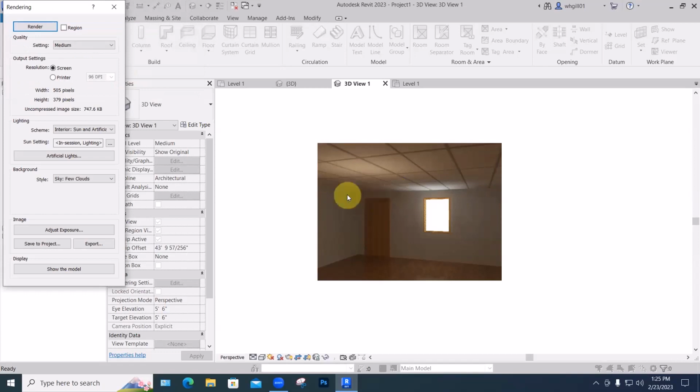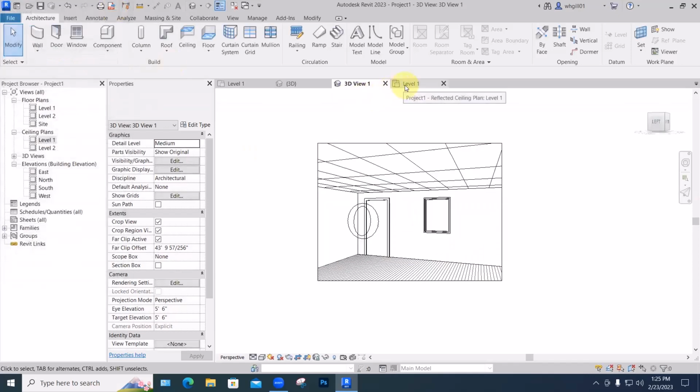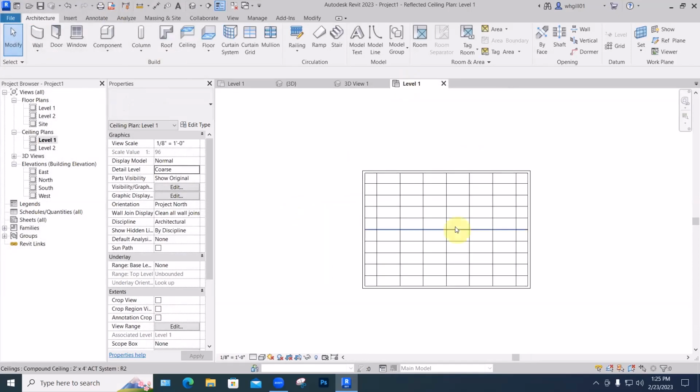And here's a trick I discovered. If I put those light sources behind the camera, then I never end up seeing the hot spot. So let me just quickly do that. Ceiling plan. Oh, the reason we don't see that anymore is interesting, is that if you remember by default, a ceiling plan sort of looks up from 7'6", and our light fixture is down at 5 feet.